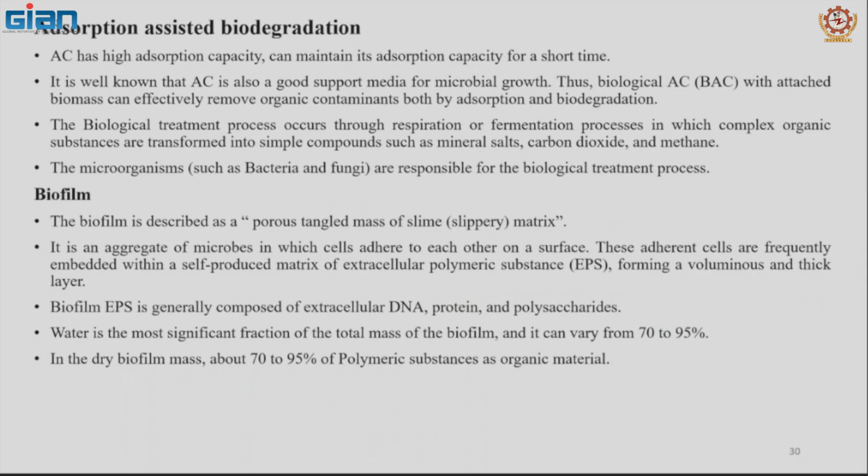So this is the adsorption assisted biodegradation. And as far as the biofilm is concerned, the biofilm is described as a porous tangled mass of slime or slippery matrix. It is an aggregate of microbes in which cells adhere to each other on a surface. These adherent cells are frequently embedded within a self-produced matrix of extracellular polymeric substance, forming a voluminous and thick layer.